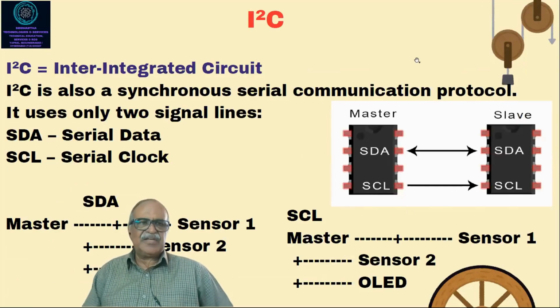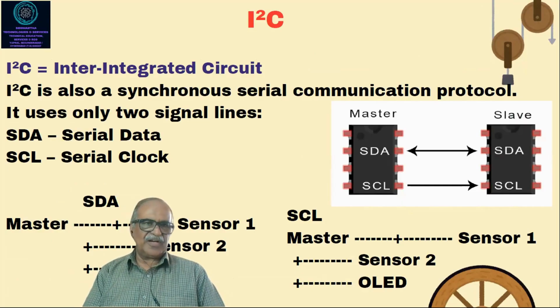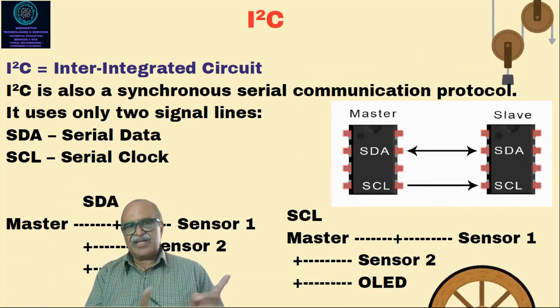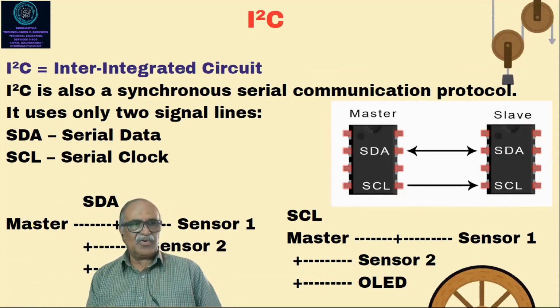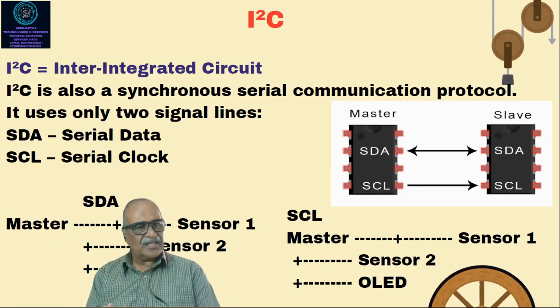What is I²C? Inter-Integrated Circuit, we call this. Please remember, I²C or I2C is the same communication protocol. Inter-Integrated Circuit, we call it. I²C is also synchronous. Please remember, it is not asynchronous. It is a synchronous serial communication protocol. It uses only two lines, two wires. One is called serial data, that is SDA, and another one is serial clock, that is SCL.